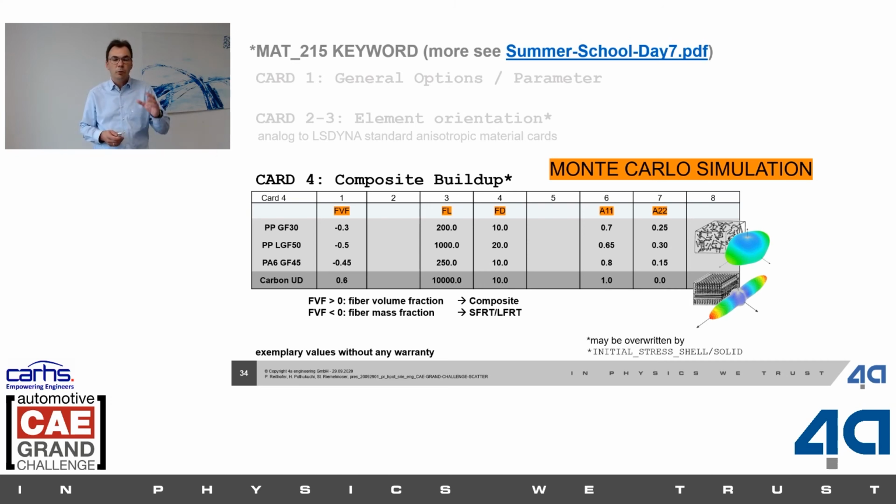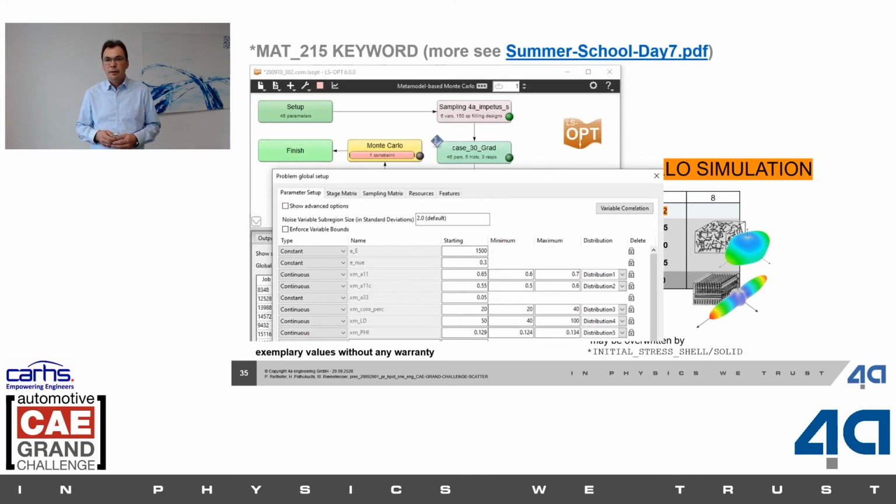If you're more interested in this material model, I have given you a link to our summer school where we are talking about it in more detail. Here you see then the automatically generated LS-DYNA keyword out of Valimat, where we then can define this distribution for these fiber values.